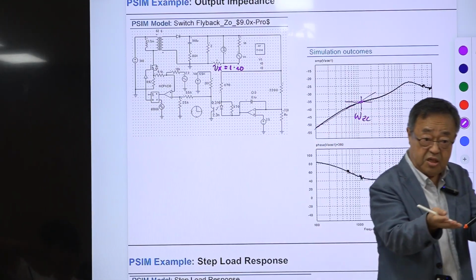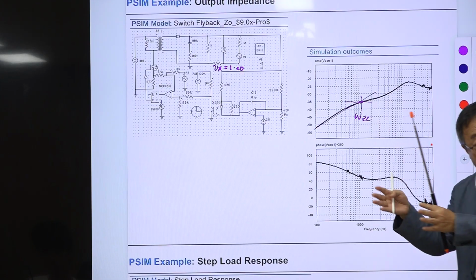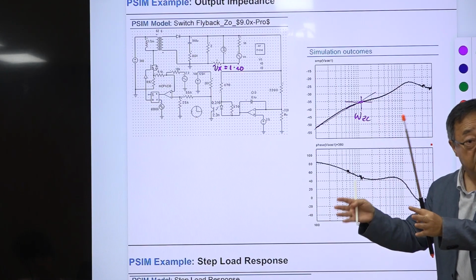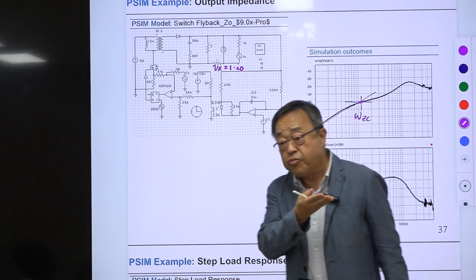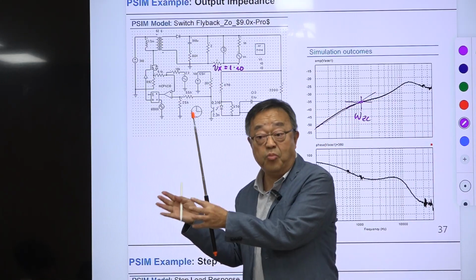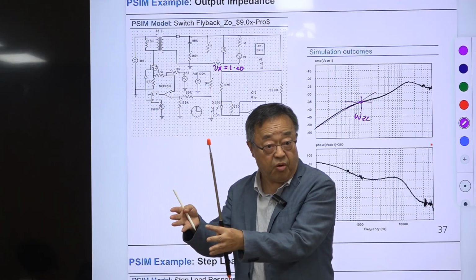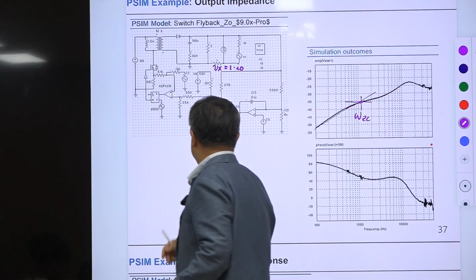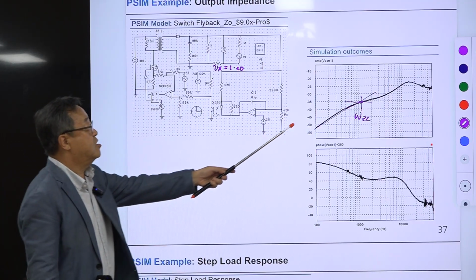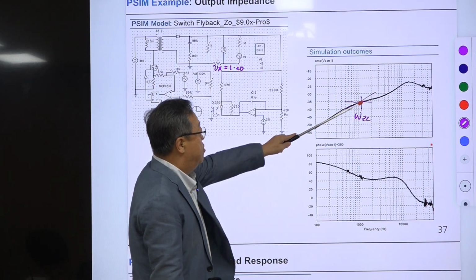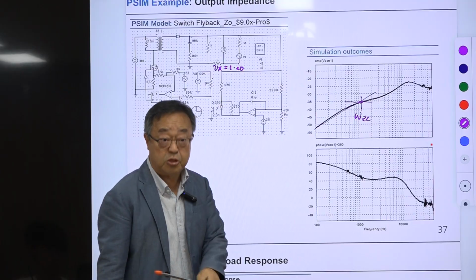during this process, it comes in the denominator because 1 plus Tm is everything. The output impedance is determined by 1 plus Tm. You kick out 1, then Tm is in the denominator. So a zero becomes a pole, because the load is swapped. Okay, so this compensation zero works as the pole here, and this pole determines the speed.